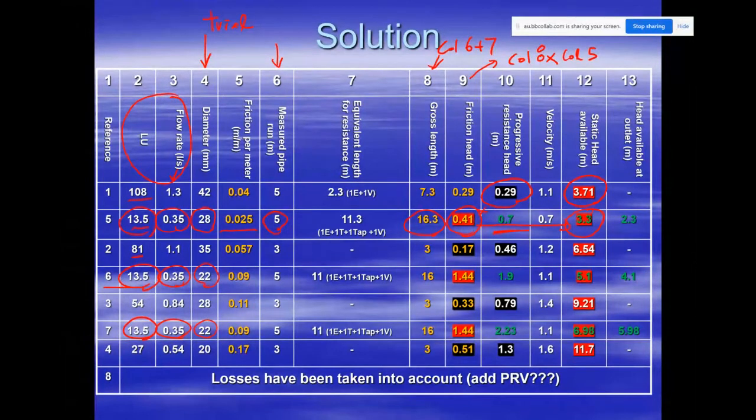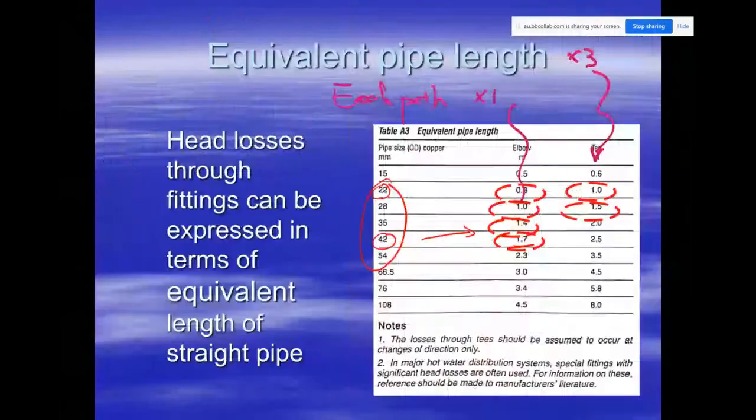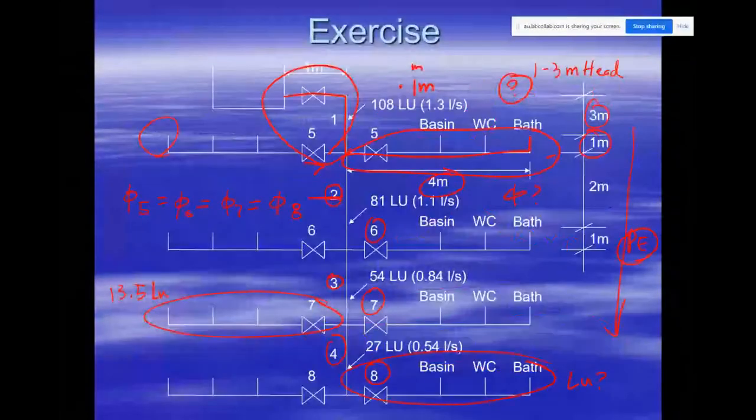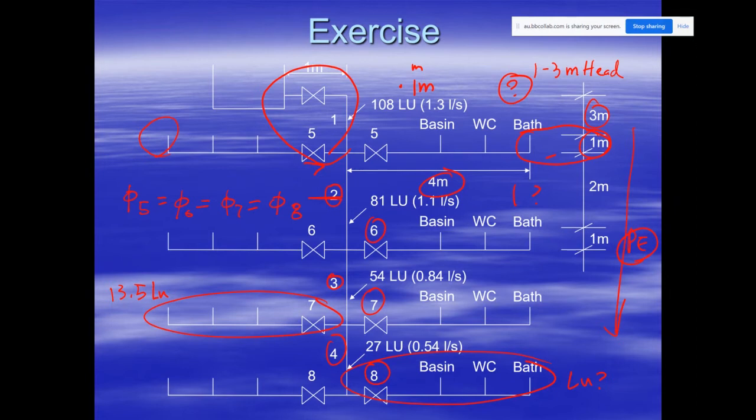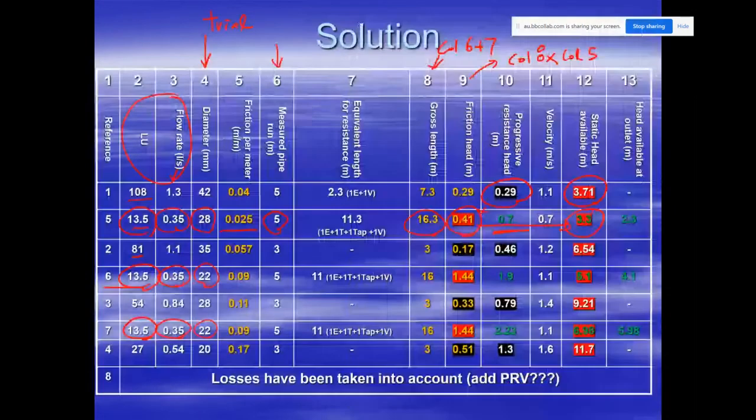Understand? Now, if this one is 3.3, but when you go through this schematic diagram here, 1 meter. That means this is the loss of energy, because the water will be moving upward. You can't gain the gravity force, you lose the potential energy. So at the end, minus 1, so 2.3. This is the discharge pressure for pipe section number 5.